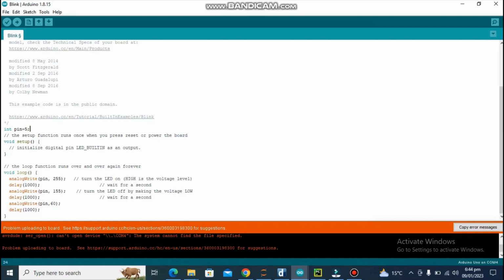However, we are declaring this pin 5, means we have to tell that we will be using pin 5. It can be done only if we declare it before our program. So here we have declared this, you can see. Now the setup portion is just empty, but we need to write setup. Without this part of code, our program will not work. So make sure you write this.